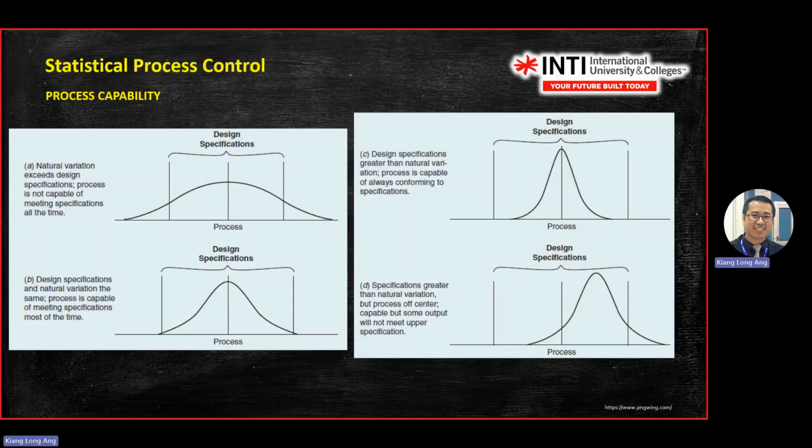Okay. So if you're in the industry later and you see this kind of chart, it means you need to do calibration on the machine. The central point of the machine is out already. You see the distribution is actually a normal form, but the mean point shifted to the other side, the right side. So you need to do calibration, right? Or usually your reference point is out, or the jig has a problem. The jig reference point has a problem. For example, in metal stamping, this means the jig location, one layer and another layer, shifted. Maybe one pin is broken, so the whole stack of the jig shifted. Then the whole block shifted.